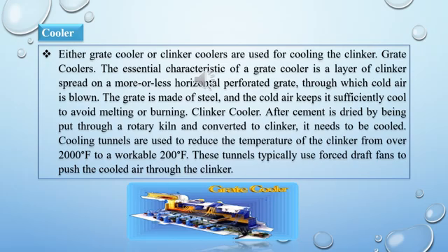In the grate cooler, the clinker is spread over the grate, which is a horizontally perforated grate, and cooled air is blown through it, which cools the clinker. And in the grate cooler, different tunnels are used, which use forced draft fans to push the cooled air and cool down the clinker. So students, it is clear that there are two types of cooler, the grate cooler